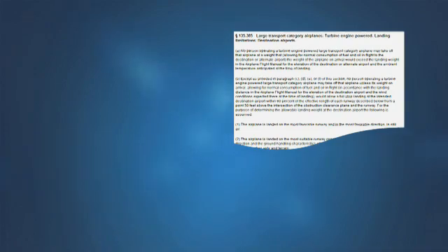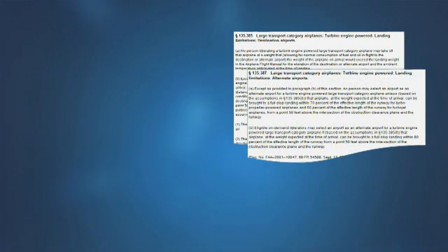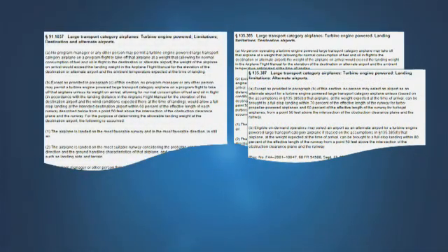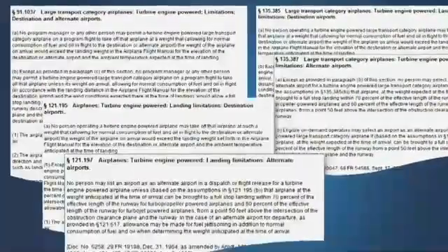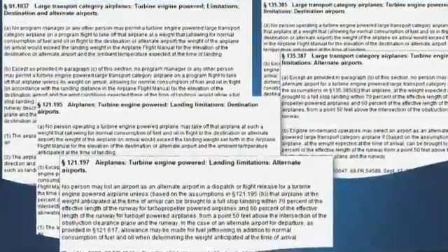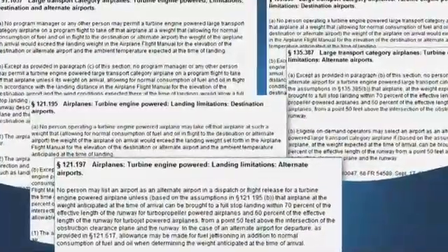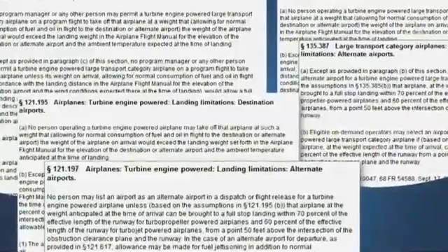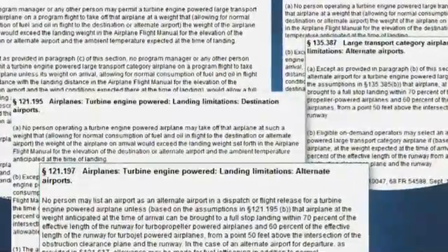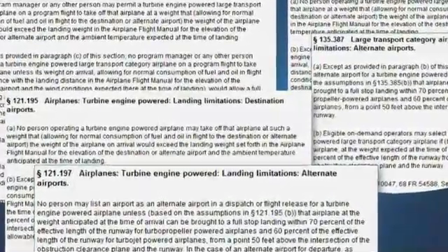The landing distances determined during certification are established with full awareness that operating rules require additional factors to be added when determining the minimum operational field lengths for landing during normal line operations. The operating rules for Part 121, Part 135, and Part 91K require that the landing distance demonstrated during certification remain within a specified percentage of the runway length available for landing at both the destination and alternate airport. As a result, these rules establish a minimum operational field length for landing.